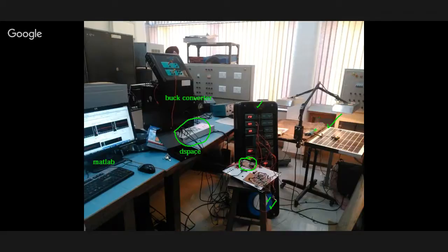The output voltage of this PV is around 17 volts. So in the morning also I told you this 17 volts you can't directly give it to your D space. Like say D space, around 0 to 10 volts it is acceptable. Even you can go till 20, but now you have given the 17 volts directly, and in case some short or something occurs, your system will get burned off.